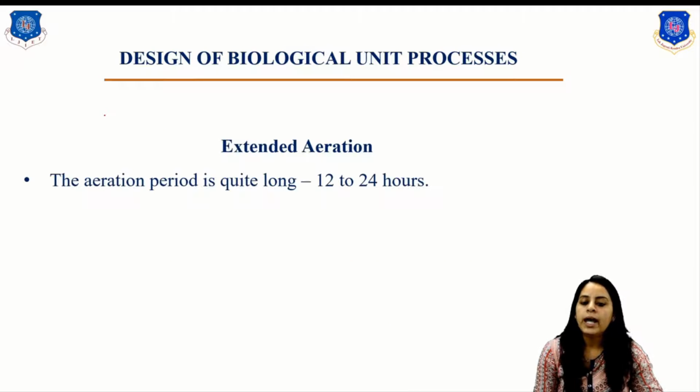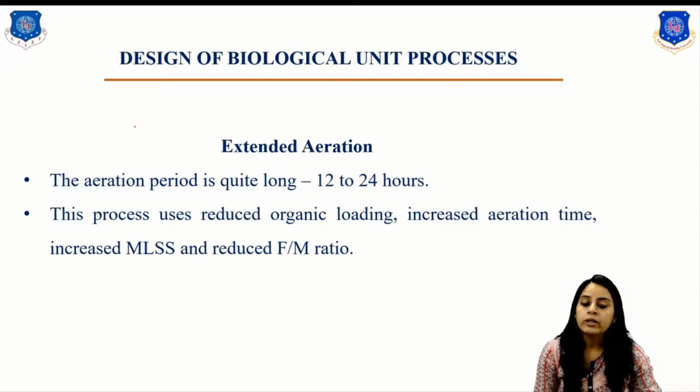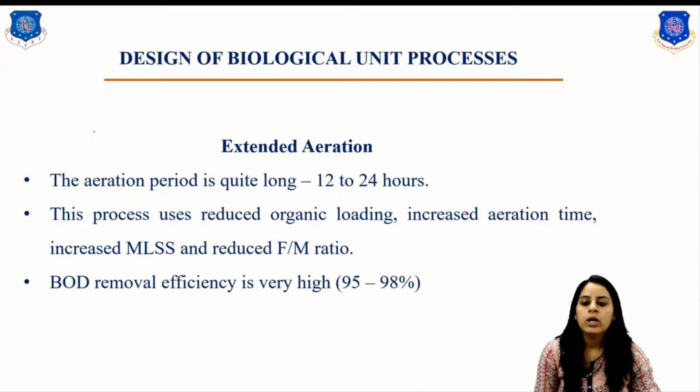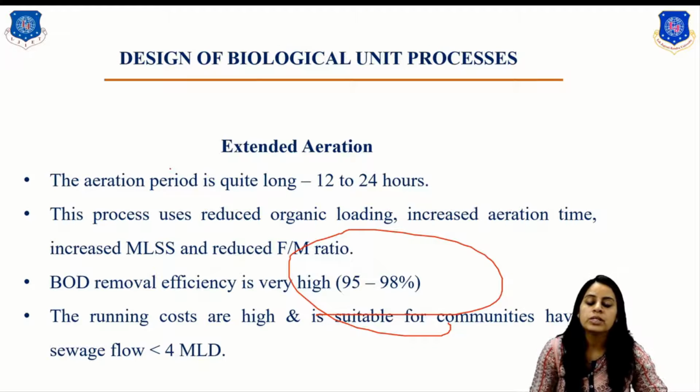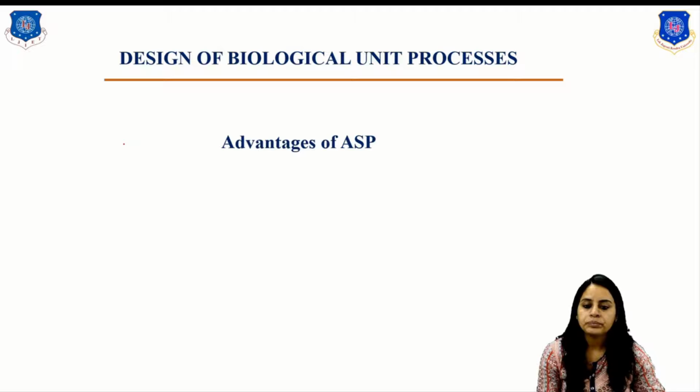Okay, the extended aeration. It means the aeration period is quite long, 12 to 24 hours. This process uses reduced organic loading, increased aeration time, increased MLSS and a reduced F by M ratio. Then the BOD removal efficiency is very high, about 90 to 95%. The running cost is very high and it is suitable for communities having a sewage flow of less than 4 MLD.